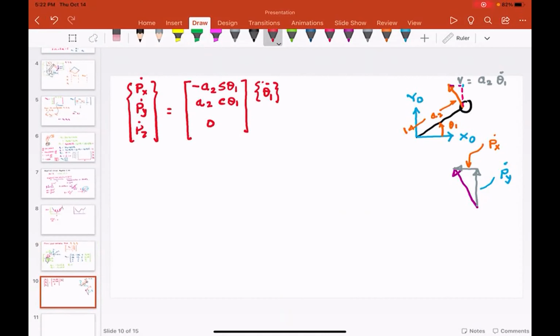So you have a Jacobian and you have a joint velocity vector. This is related to the linear velocities. But please understand, this robot has angular velocities as well. This is rotating. So how do we deal with the angular velocities? And remember this, every time you want to find out the angular velocity of the end effector, it's super duper simple.